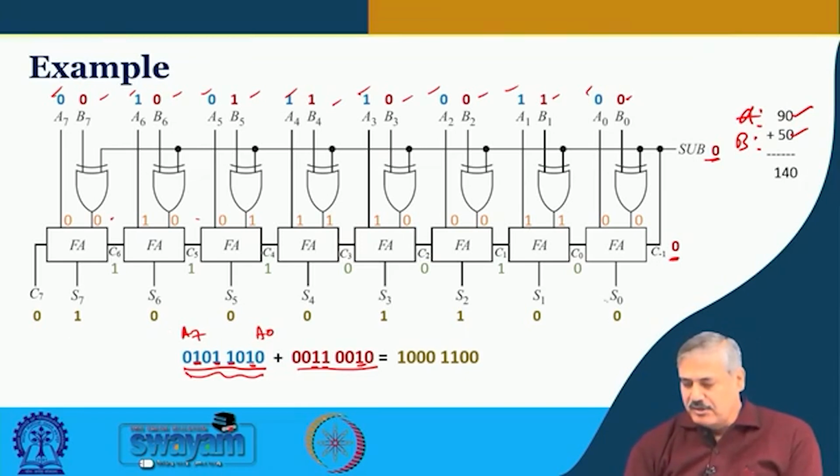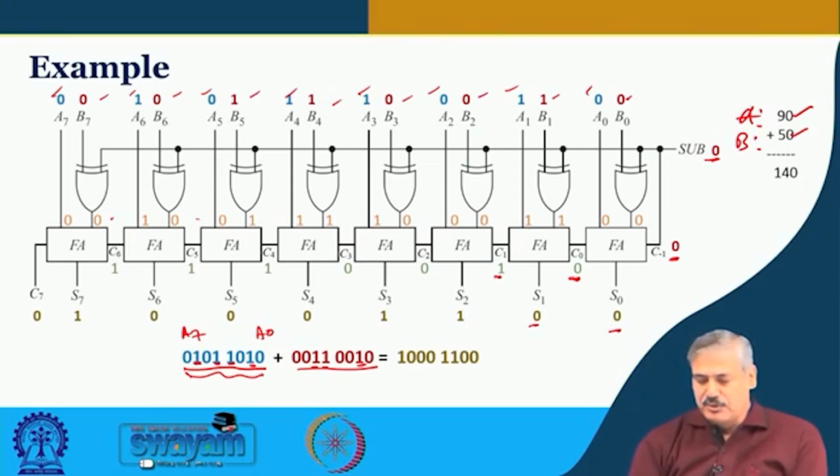So, 0 0 0 over here. So, this intermediate carry output is 0 and sum is also 0. So, this is 0, this is 1 and this is 1, right. So, sum is 0, this carry is 1. So, this 1 0 0 for the full adder.